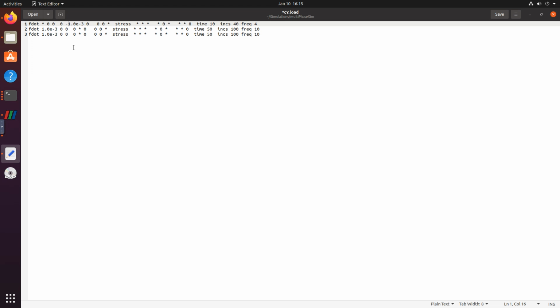Okay, and z is still open, so it will deform to any value that I want. Now what I need to change is, instead of stress being unidentified, in this case I have to define this as 0 and this as static.